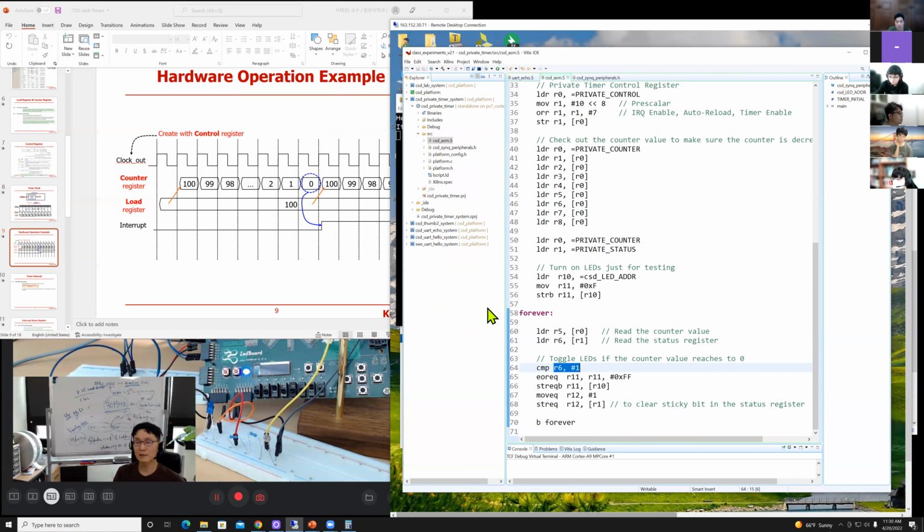Then the whole countdown reaches 0, right? So you are doing that operation. EQ, remember EQ? The compare instruction sets flags N, Z, C, V in the CPSR register. The next instruction checks the flags to determine execution or not. So, status register is equal to 1, meaning this point.